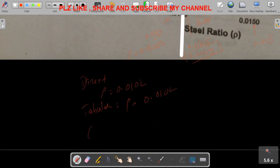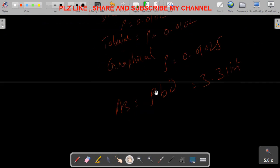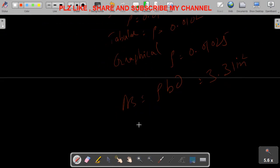Similarly, in the graphical method the rho value is also approximately 0.0102, which is close. So my area of steel will be rho times bd, the same amount of steel, 3.31 square inches. You can see all these three methods give me the same reinforcement, and we will provide 6 number 7 bars, or we will provide 8 number 6 bars.